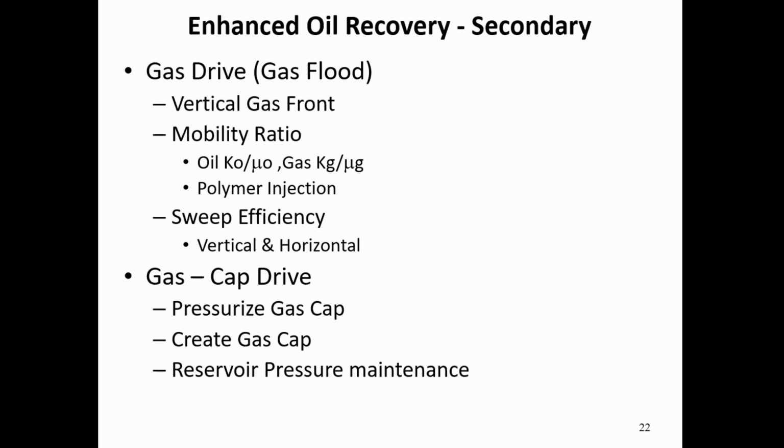The slower and the longer the stay of chemicals inside the formation, the better the sweeping efficiency and the higher the recovery factor. Because sweeping efficiency is part of recovery factor. Recovery factor is made of two elements: the sweep efficiency multiplied by displacement efficiency. Make a note of that. Recovery factor is equal to the sweep efficiency multiplied by displacement efficiency.